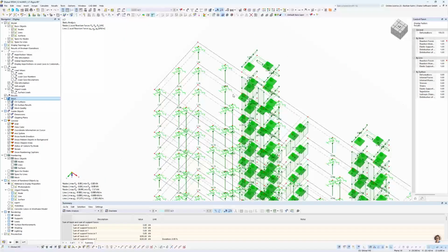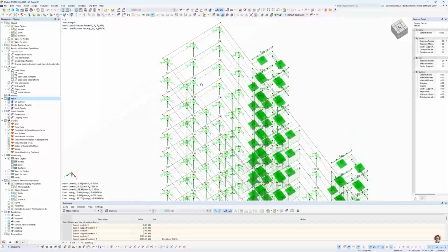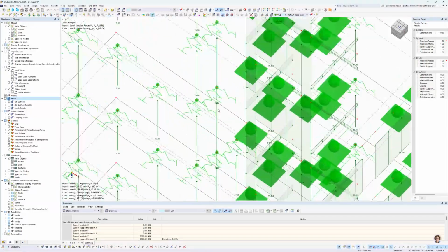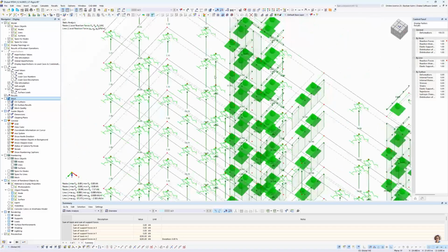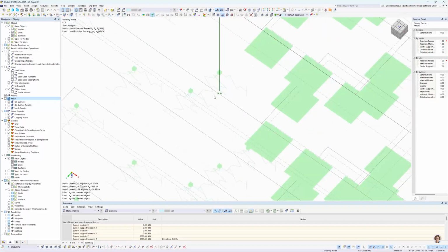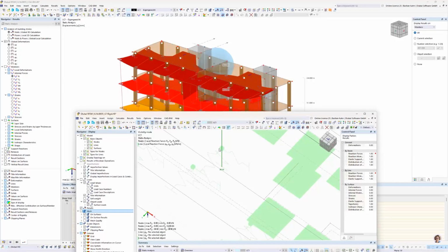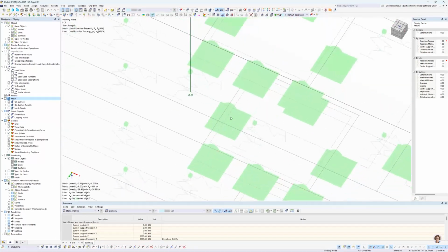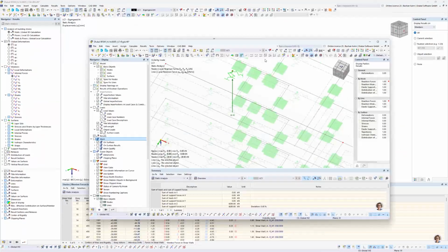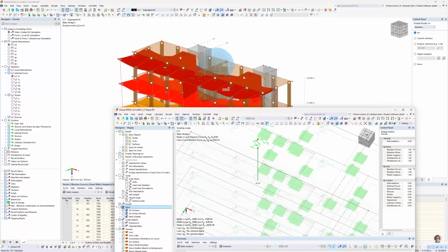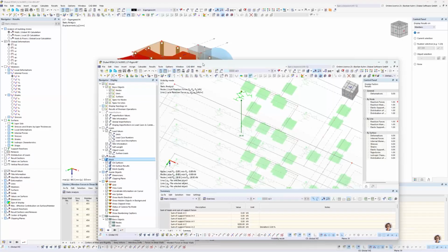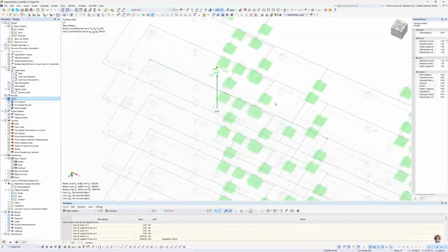and get out of this rendering for the center. So you see here, not so good to see, but maybe we do it similar to what we did before, just show this one. So it's 28.9, which is the same value that we had here for the center column. And that's the point where we're looking at. And of course, it's the same vertical force because that is the model in the back of this, when you define this load transfer type, semi-rigid or rigid in this case.